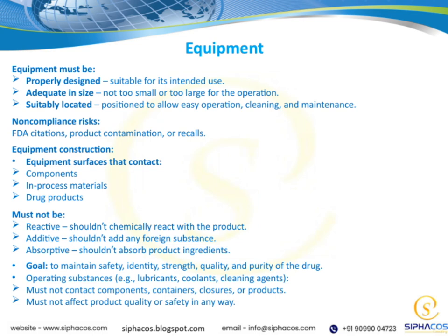Let's talk about the construction of equipment. Surfaces that come into contact with components, in-process materials, or the final drug products must be carefully designed. They shouldn't react chemically with the product, which means no reactive surfaces. They also shouldn't add any foreign substances, that's the additive aspect, and they shouldn't absorb ingredients, which could alter the product's quality. Our main goal with all of this is to maintain the safety, identity, strength, quality, and purity of the drug throughout its life cycle.